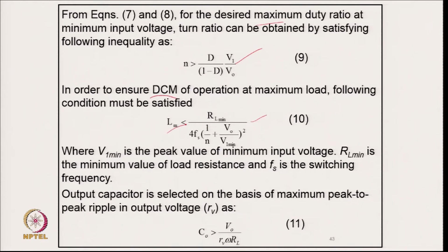You should keep the inductance lower than that; only then will you go to DCM. Of course, this should be ensured at maximum output power with minimum input voltage, because that corresponds to the maximum current appearing. Even at maximum current it should be discontinuous. Of course, the output capacitor corresponds to your output load current divided by twice the frequency or the ripple factor.